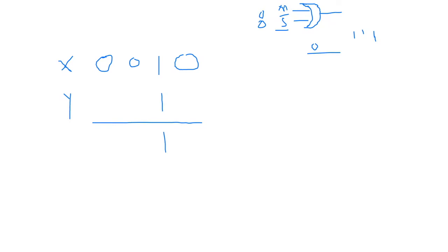If it is a 0 and we still want to write to it, and we send a 1 to it, we expect the output to be 1. So in this case, we are using an OR. This is an OR gate that we use to set the pin. To read the pin, we use an AND gate. To set it, we use an OR gate. We will talk about a case where we toggle the pin some other time.